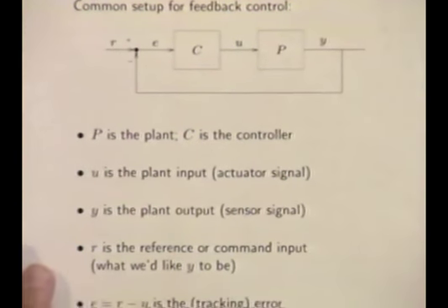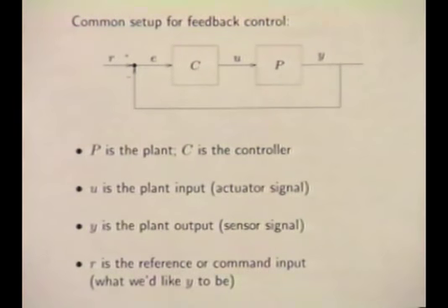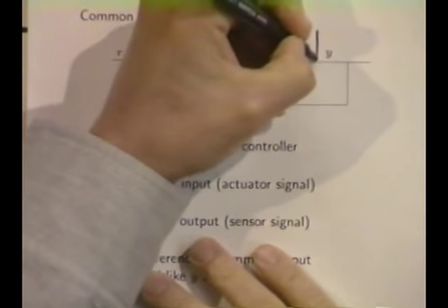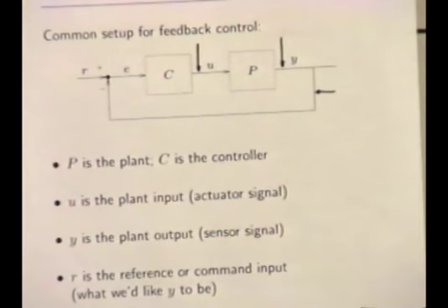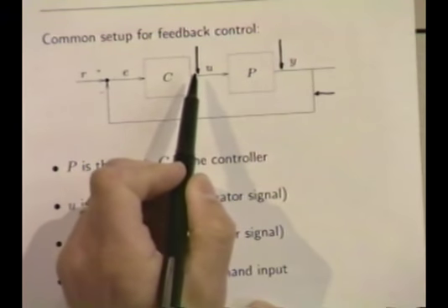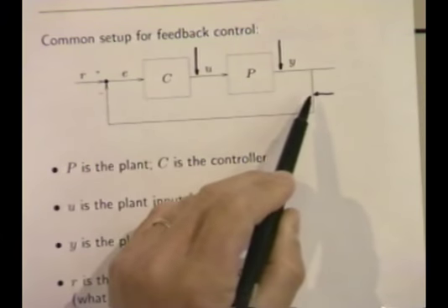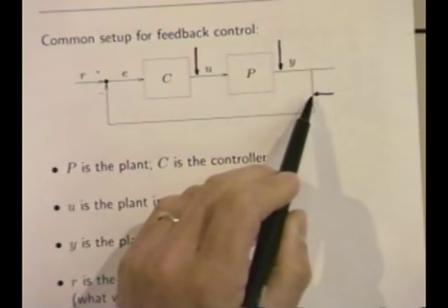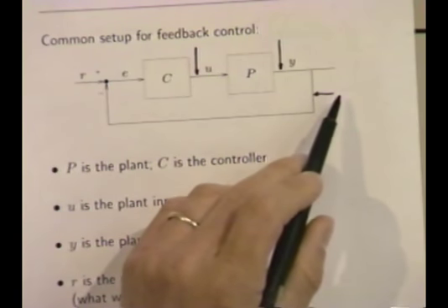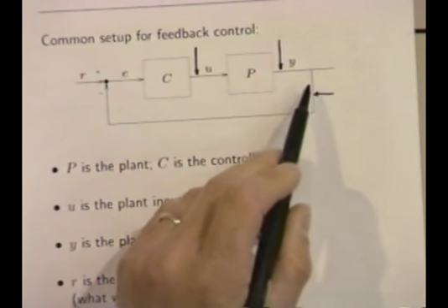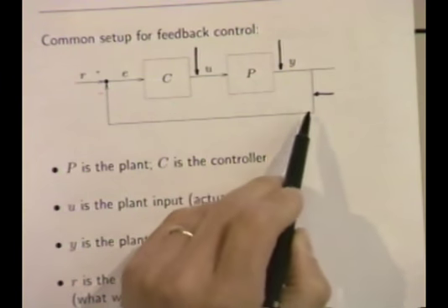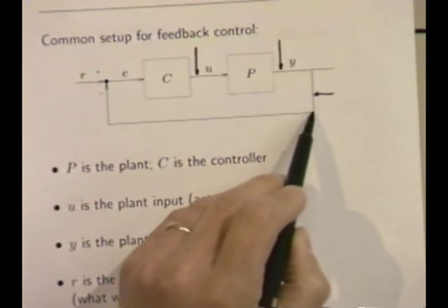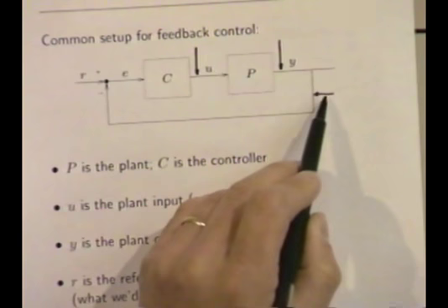Okay. So this is the picture here. Now, you can also do things like add disturbances. For example, you can add a disturbance there, you can add a disturbance there, you can add a disturbance there, and give them all sorts of names. For example, you might add this, and this could be wind gusts. Okay? You could add something here, and this would be, in fact, sensor noise. This could be your gyroscope, your inertial navigation system error would be added there. Because this is really where you are, and this signal is where your inertial navigation gyroscope assembly tells you are. Hopefully they're very close. But if they're not exactly close, you call the difference your inertial navigation error.